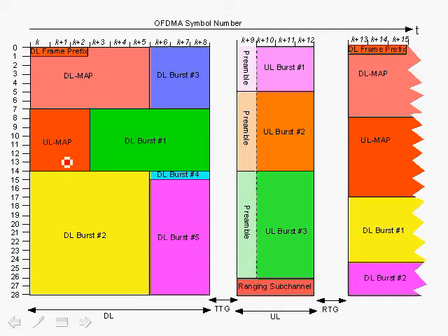Therefore, once the subscribers receive and decode the uplink map, they'll know what rate and what region to use to send their data. So, for example, in this uplink, we're showing 3 bursts, in different colors from different subscribers, and these regions are specified in the uplink map. So this makes a lot of sense in getting this OFDMA to work.